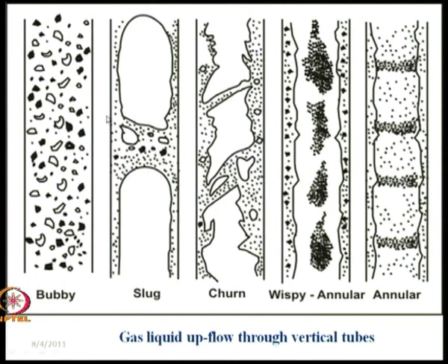Now, remember one thing, once these bubbles are formed, their shape does not change further with more introduction of air. What happens as we introduce more and more air? In bubbly flow, both the frequency as well as the size and the shape of the bubbles were changing. In this case, once the bubbles have been formed, their shape does not change. If we introduce more air, the bubbles become longer and longer. But this hemispherical nose and a cylindrical tail, the axisymmetric bullet shaped shape, remains unchanged.